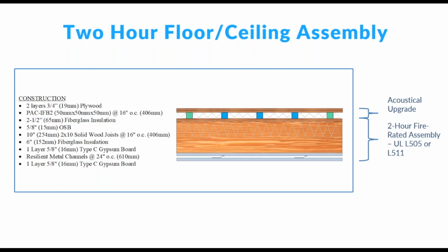And I did this as an acoustical consultant on a project. I was helping design sound isolation and everything for a recording studio that they wanted to build directly above a brew pub. Great if you're the musician recording in there and you want to go down and grab a beer during your break, that's awesome. But when in the brewery they're dropping kegs and moving kegs around and you've just recorded your perfect track, but it was destroyed by this loud thump and bang from down below, not so awesome. So we had to do all the isolation on the top side and we did a floating floor there.